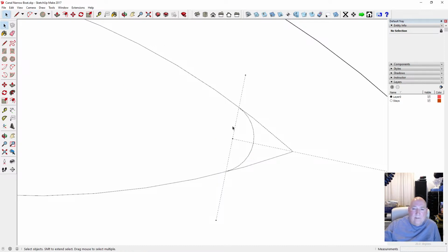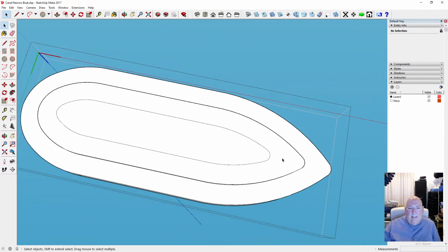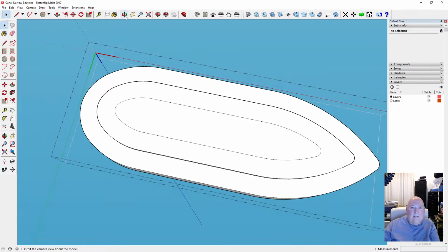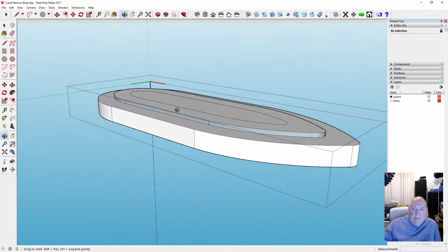Okay, so we've got a smoother area. Let's get rid of that and that. Okay, so yeah, we could mill that now. So we've got our pocket. So we've got an area about 115 mil by 20 mil, and we want to keep the 10 mil space. Yeah, 10 mil, 10 mil. Okay, so then we can pocket this down deep now.